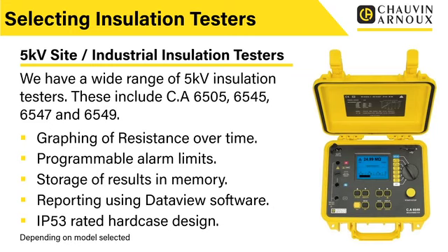Now, we can also set programmable alarm limits. So if the insulation is below a certain value, it will give you a warning, so you don't have to look at it specifically and read. You can set up the alarm. So if you're carrying out a lot of tests, maybe on motor windings, you can set the alarm, listen out for the alarm, and it will tell you, rather than you having to keep an eye on the screen all the time when you're doing it.